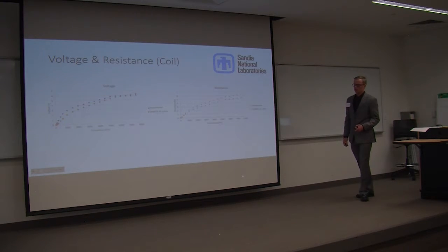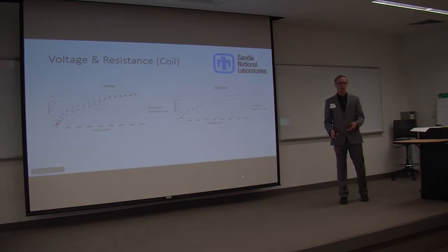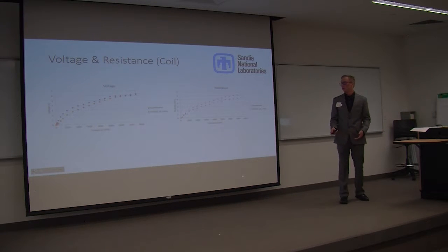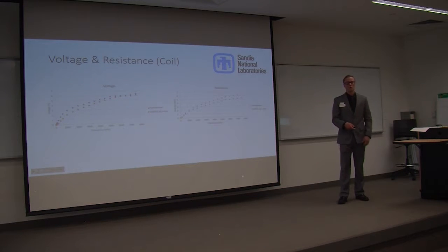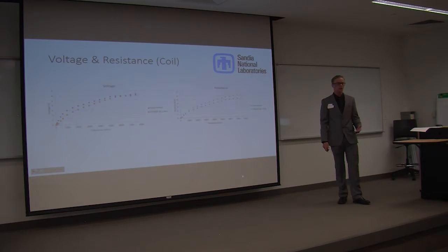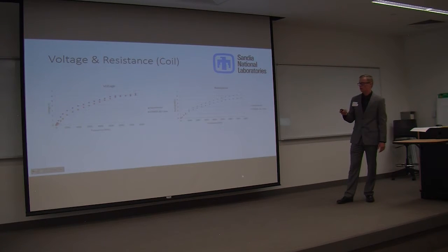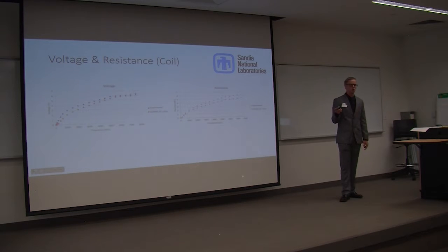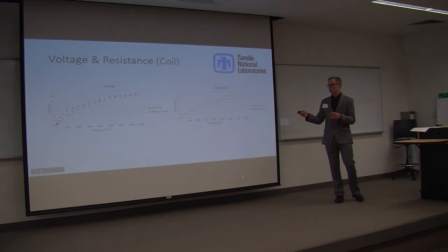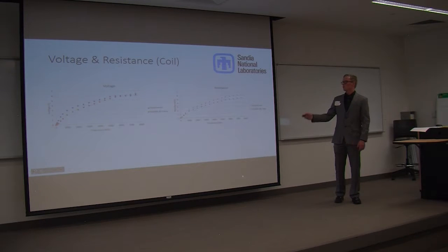The next aspect isn't nearly as interesting, just because the properties of copper are pretty well known, but I'm able to analyze the voltage and resistance of the coil by having the current that I inputted manually at 1 amp, and using Ohm's law. I found resistance by having COMSOL solve for the resistance, and then using Ohm's law, where V equals the current times resistance, which with the current at 1 amp, is the max induced voltage on the coil.